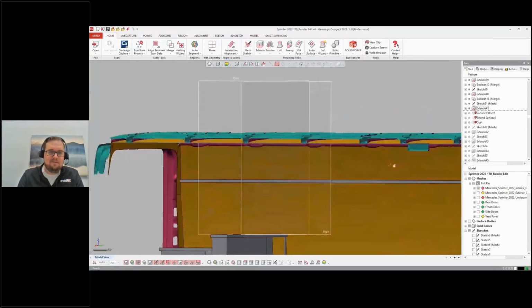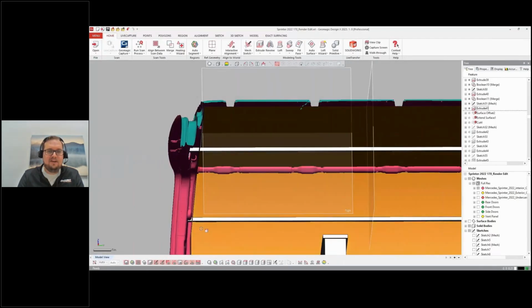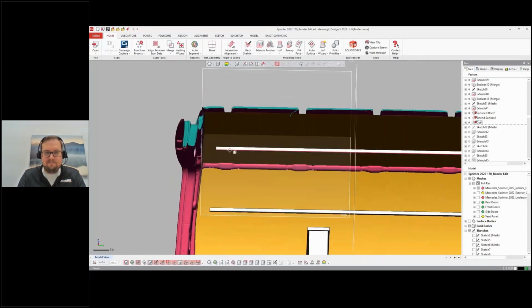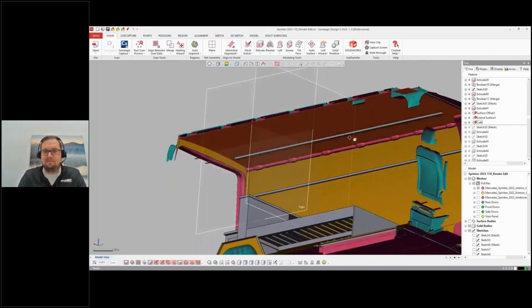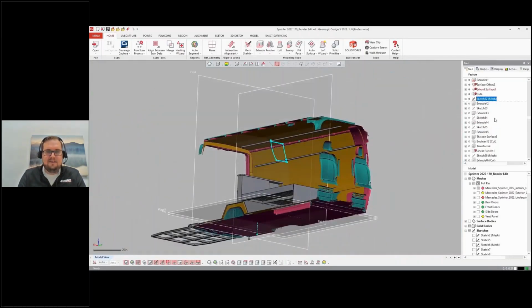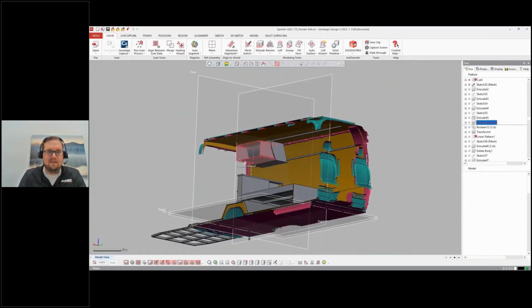And then we can just extrude them right in here and trim them to fit. So I've just run them long in case I want to run my cabinets. I'm going to trim them off, and then I'm going to start modeling that cabinet in here. So we're going to hide that electrical, tuck it right in behind our cabinet. You can see it's got a little bit of clearance on the rear.